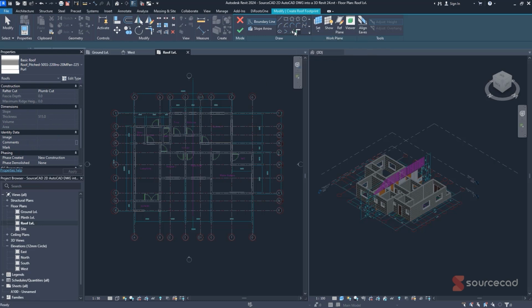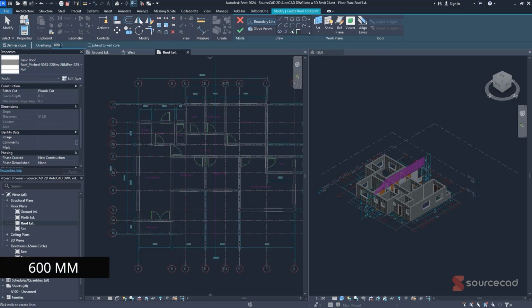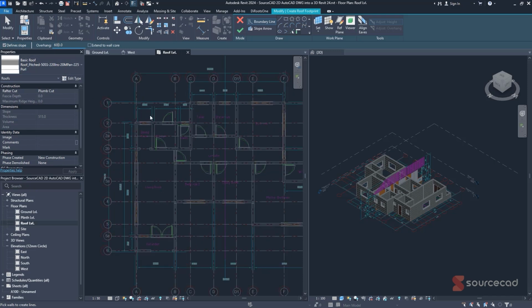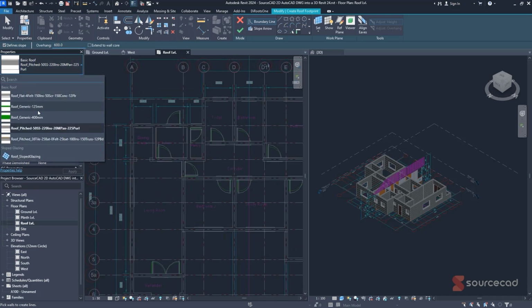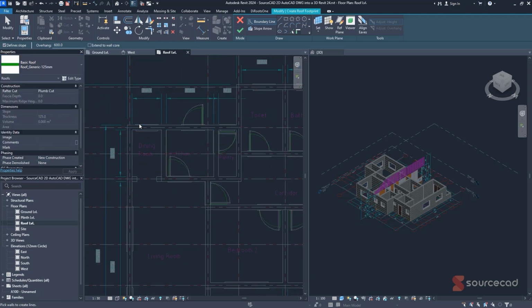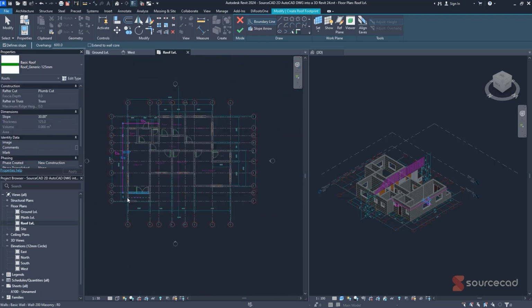So you can either use peak walls or peak lines. So I prefer using peak walls for now. Using an overhang or an eave of 2 feet or 600, I can define my slopes now, or I can define them later. So let's just use define slope, change the material of the roof that you prefer. Maybe just use this one for now. Then just click on that wall.